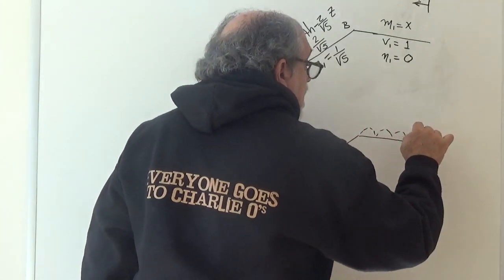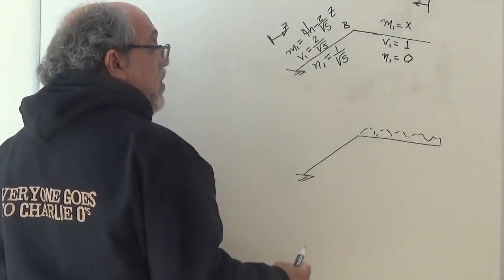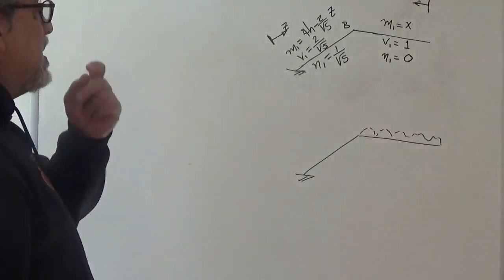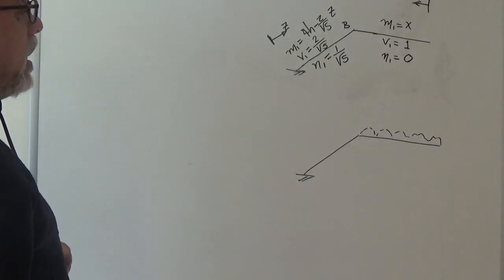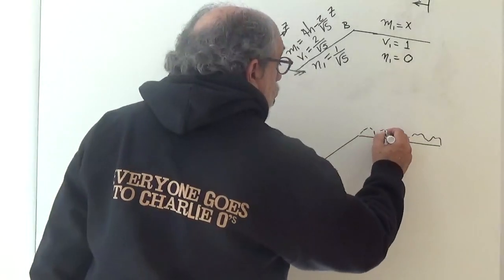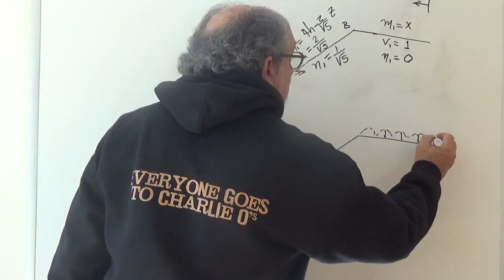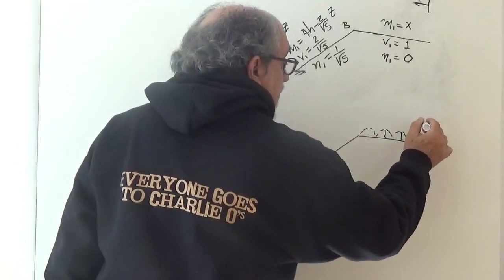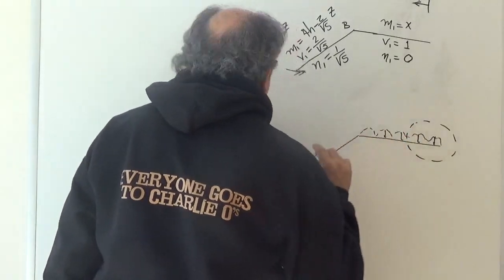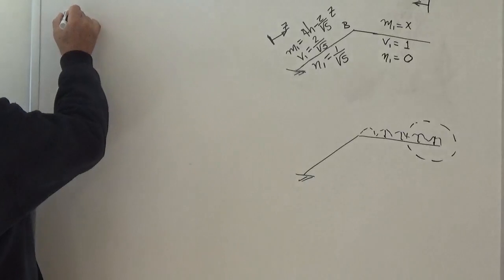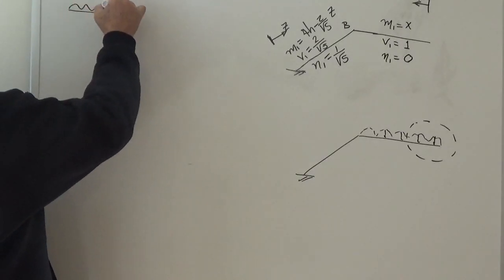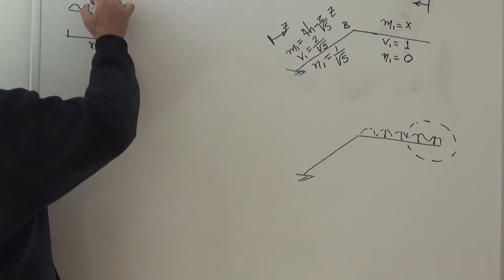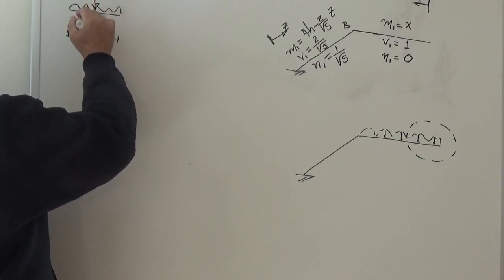The load is here. Our first free body diagram is just like before. We don't need to make decisions regarding sign convention or free body diagrams or coordinates, because we made all those decisions on the one load. So taking this free body diagram, we find this with the load W. This distance is X. This load is WX.